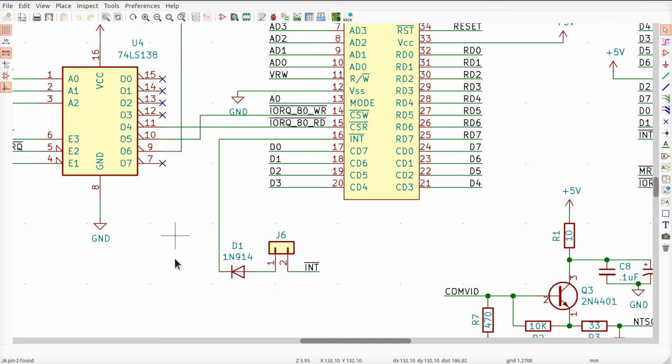But looking ahead a little bit, if we can't get that to work, it's not going to. Point is, you can't have mode 0 interrupts coming from one device and mode 2 from another. This is a galactic setting. It's a one and done type of thing you do on your Z80.